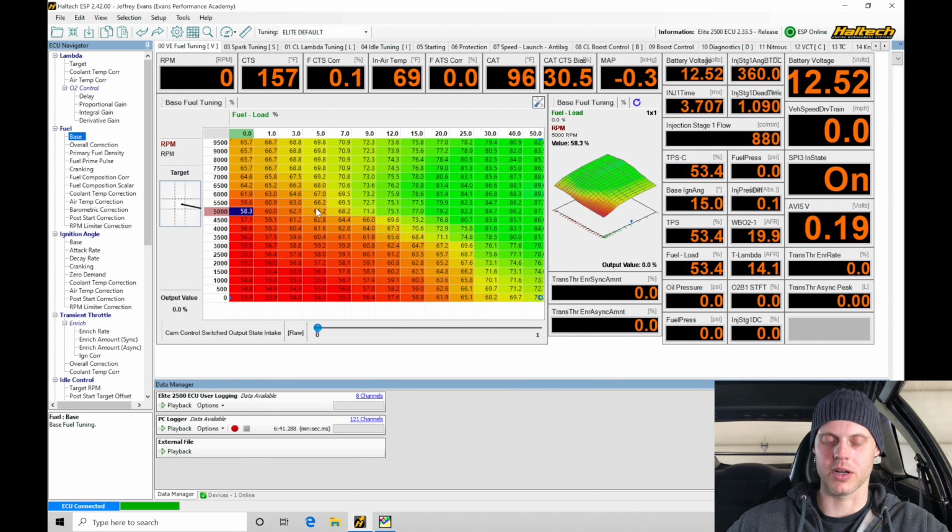If we jump in here, now we do have a couple things I want to mention here. We do have two VE tables, one table here, we can see the dot here is at 0. That's for low cam operation. We're going to find we have a 1 here. That's for our high cam operation. This is our cam switch status, the raw status, either on or off. 0 being off, 1 being on. So 0 means no VTEC. The VTEC function's off.